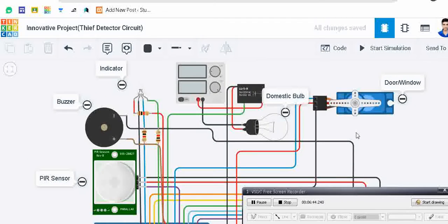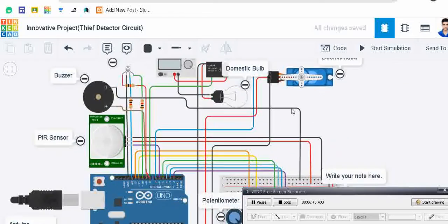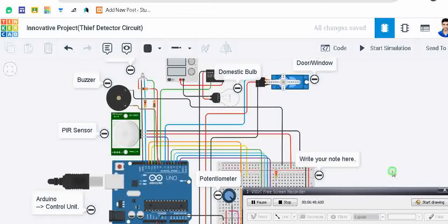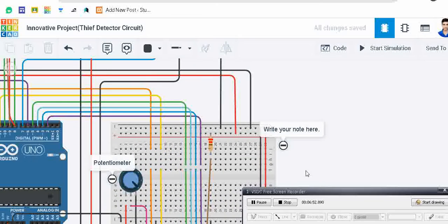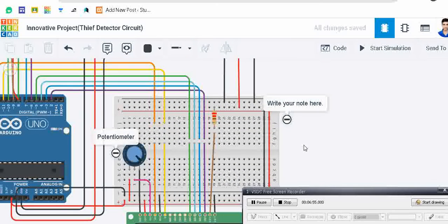So now, our next component is the breadboard. Here, the breadboard is used for interconnections of various wires. In breadboards, the upper rows are all interconnected to each other. You can see here, if we click on one hole of the negative sign row, then it shows a green row.